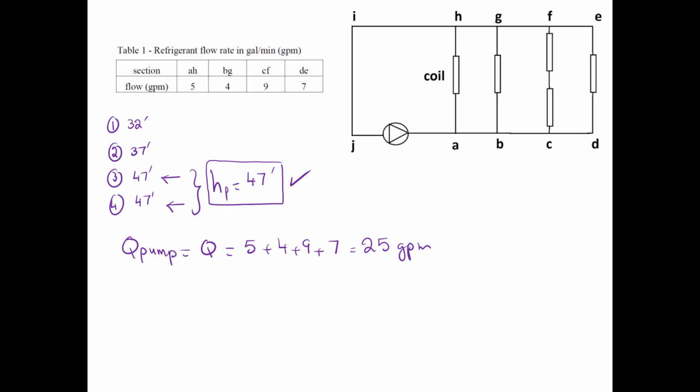Therefore, the hydraulic horsepower in HP, we have this equation. Start with it first, since I don't have the pressure in PSI. The head of the pump in feet is 3950 times the hydraulic horsepower divided by Q times the specific gravity.